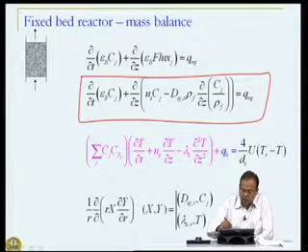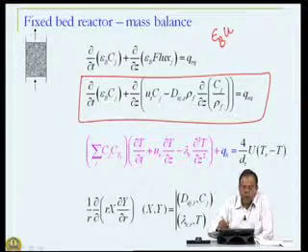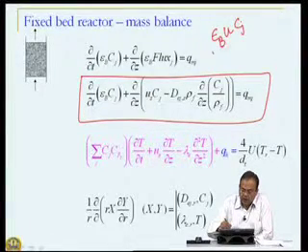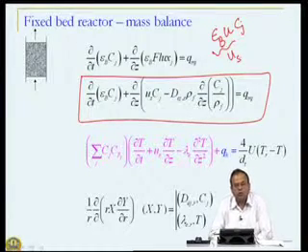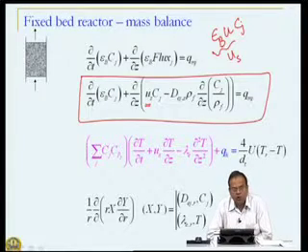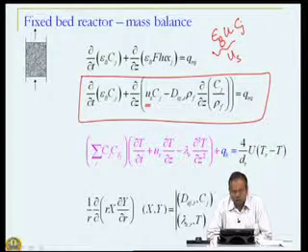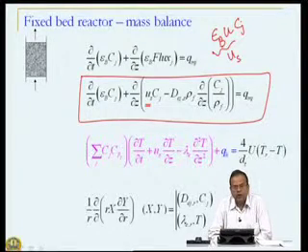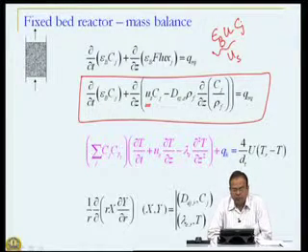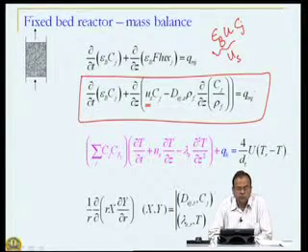Note here, what we did from that particular equation to here is we multiplied epsilon b into interfacial area into Cj and denoted this by superficial velocity. So, that is where that US comes in. This is our standard diffusive flux equation, and QMJ is my mass balance for the fixed bed reactor. I have not yet specified what this QMJ is.